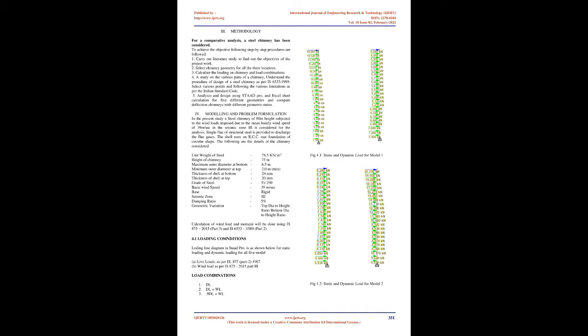Objective of study: to study the effect of wind loads on the structure and to determine the loads that are more effective on the dynamic behavior of the structure. The study will be more focused on the deflection of the tall chimney due to wind and earthquake, and the analysis done will be the dynamic analysis and the static analysis. Deflection is also the governing factor for tall structures. Depending upon the type of structure there are different permissible values of deflection, thus the study will keep deflection within permissible limits for all the diameters considered.